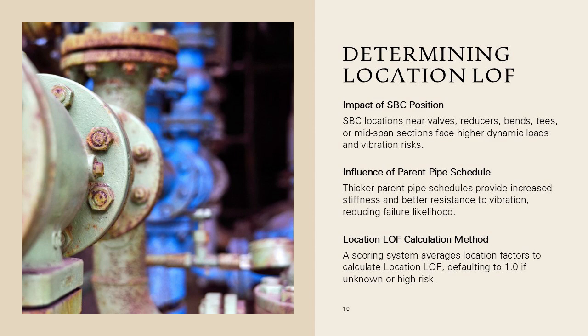The methodology uses a scoring system to calculate the mean of location-based factors, resulting in a location LOF value. If the main line LOF is unknown or equal to or greater than 1.0, the location LOF defaults to 1.0, indicating that geometry will dominate the final assessment. This approach ensures that SBCs in high excitation environments receive appropriate attention during risk evaluations.